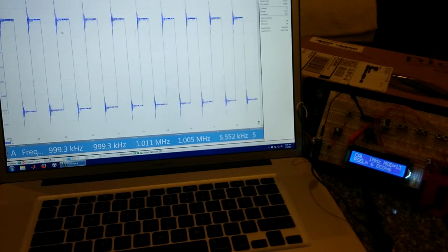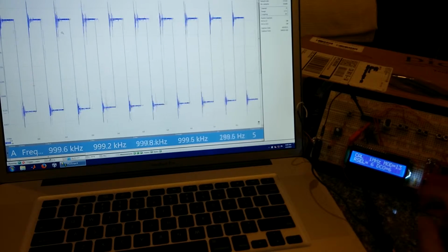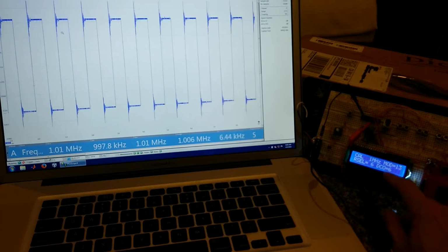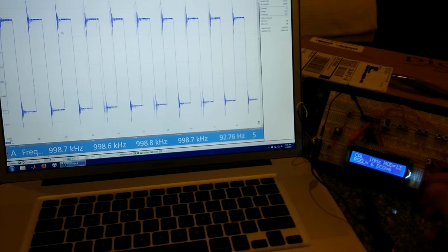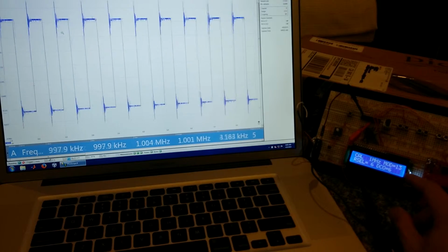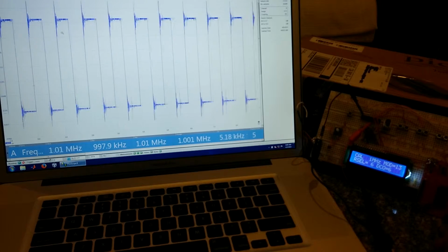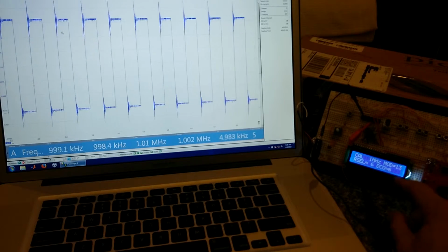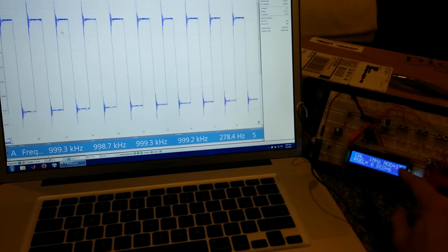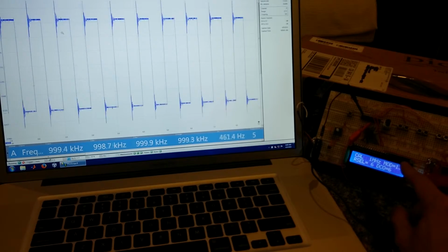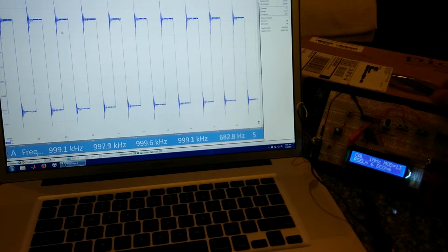And what the mod does is it breaks up the steps from the DCO into 32 different segments. And for 32 minus 13, we have 19. So for 19 of the segments, the DCO value is at 6. But for 13 of those segments, the DCO value is DCO plus 1, or DCO 7.